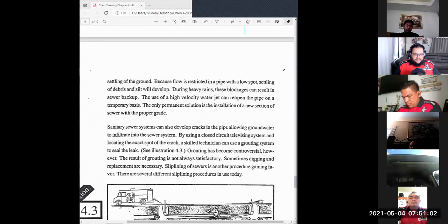Yeah, sure. What Ken's saying. Sometimes you buy PVC, or ABS is the worst, I should say. You leave it out in the sun while you're digging up your trench, and that pipe starts to take the form of the ground. If you've got a pretty good sag in it, they have you turn it on its side, so now the sag is sideways, and all you do is straighten it out while you're in the trench. So never lay the sag on its back or on the high spot of it. Put it on your side and then straighten it out from there.